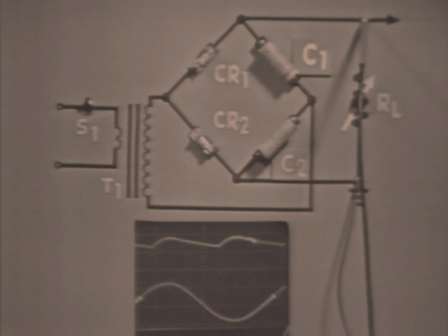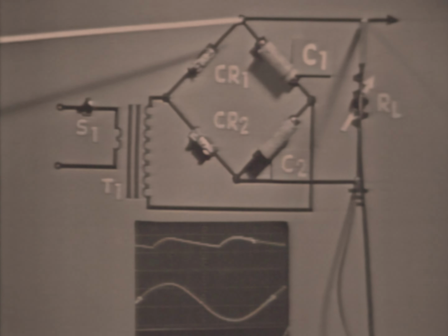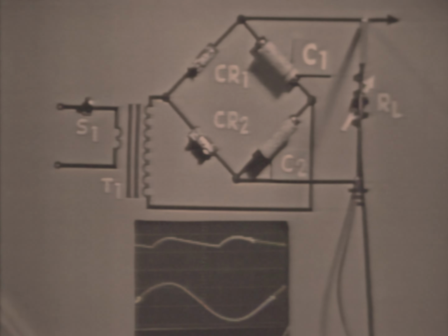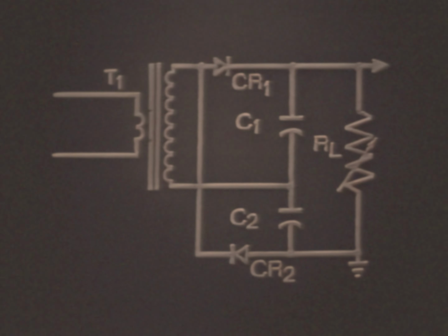So what we've accomplished by placing these 2 capacitors in series, at C1 and C2, is change the operation of the circuit from a bridge rectifier to a voltage doubler. A more common way of drawing the voltage doubler circuit is shown here. Now, this arrangement shows that the voltages of C1 and C2 will add since they're placed in series with each other. Now, this means that the output then equals the sum total of the voltages developed by both capacitors.